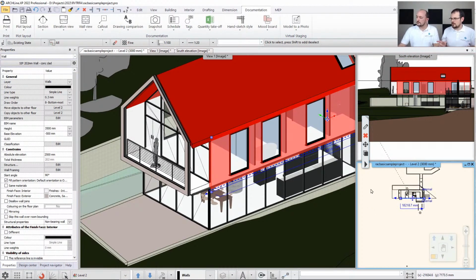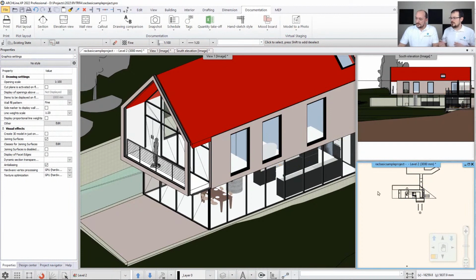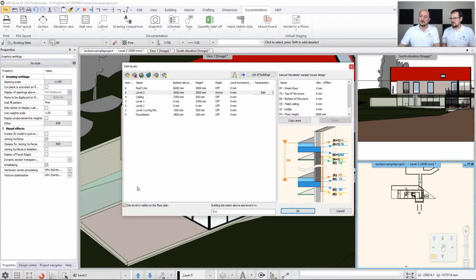You made one remark about the floor structure. So what do we see from the original floor structure here? Yes, besides, we can see the whole building built up the way it was originally designed. It is important that when you go to the 2D drawing and you click on the level designer here, you will see the same level structure, the distances, and basically all the constraints that you can define here are all there, and then you can simply edit them.